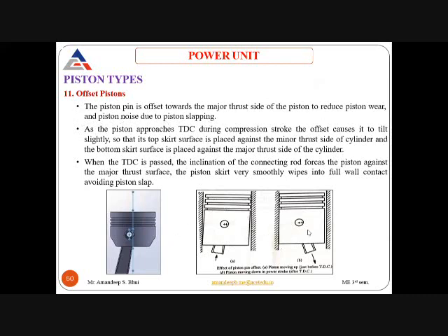By doing the offset, we avoid the piston slap, and we avoid the wear of the piston and the cylinder lining on the major thrust side of the piston.